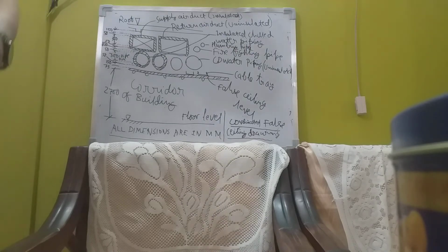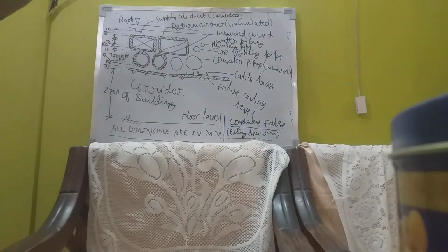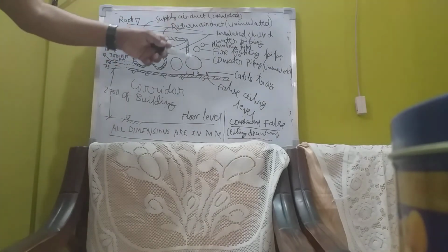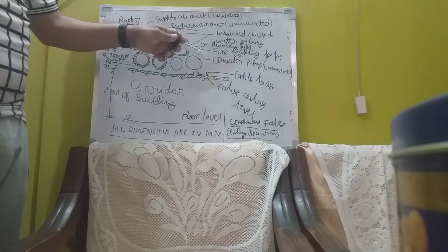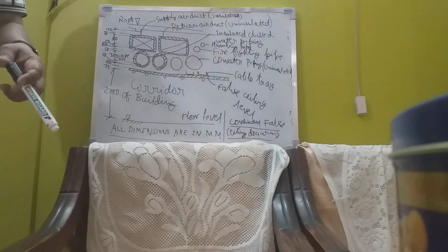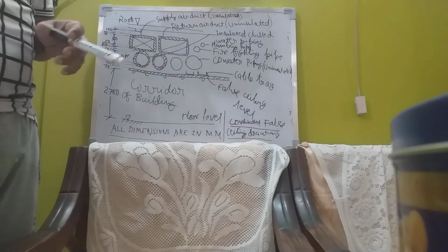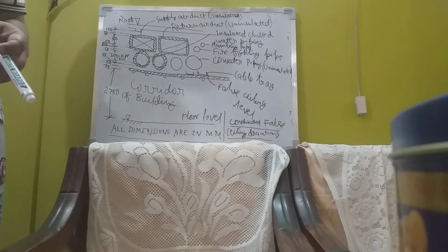You have to make the building air conditioned in the present day. Big buildings have to be air conditioned, whether hospital, shopping mall, whatever it is. So HVAC is to be accommodated, and whenever HVAC is accommodated, a big space is taken by it. There is no other problem when you accommodate a firefighting pipe. This is a small diameter pipe. The red pipe you will see running through the building is a small diameter pipe. Plumbing has 3 pipes, cold water, hot water and drain pipes, small diameter pipes.